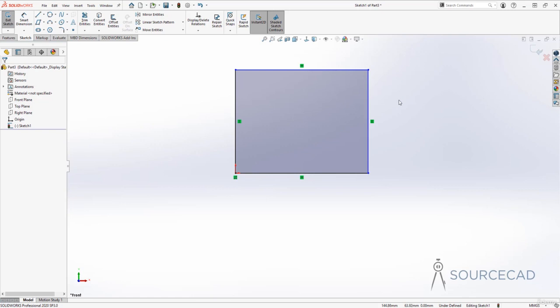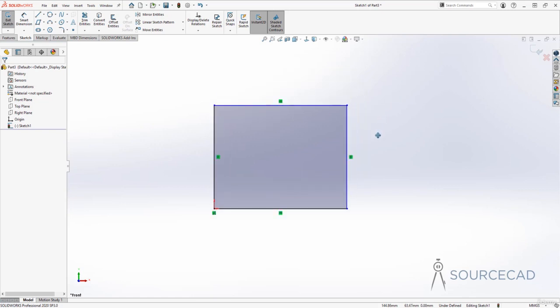But before we do that, I want to draw your attention towards this thing. Right now, this drawing is underdefined or not fully constrained. And when it's like that, SolidWorks will show you here on the status bar the status of your line. So it is underdefined. Actually, we have a couple of lines here, so it will show you the status of your geometry.